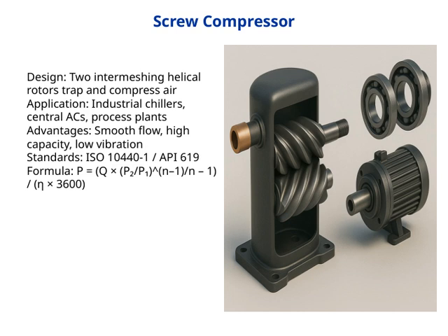They also offer high capacity, meaning they can handle large volumes of air, and they tend to operate with low vibration levels, contributing to longer equipment life and quieter operation. When it comes to standards, screw compressors are typically designed and tested according to ISO 10441 and API 619, ensuring they meet specific quality and performance benchmarks.